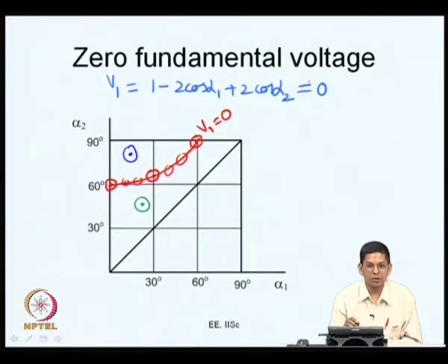So, why we consider 0 fundamental voltage is that there is a kind of continuity in the properties here. Now, let us say you consider this waveform that I have given here. If the waveform has certain spectral properties at that point, in the neighborhood of that point the spectral properties are going to be quite close to it. So, let us say a particular harmonic is very high, or let me first say that the fundamental component at this point that I am indicating here is so much. Let us say it is 0.4 per unit, and if you consider somewhere in the vicinity of this, very close to it, again it will be very close to 0.4, slightly higher or slightly lower than 0.4. Similarly, let me say that the fifth harmonic component at this point is very high. So, you can say that in the neighborhood of this point, the fifth harmonic component will be fairly high. So, if you understand several operating points corresponding to V1 is equal to 0, you can reasonably understand the points at which V1 is some small value.